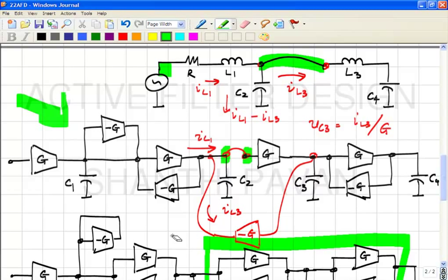You probably change the capacitors, right? You figure out two things to change. Rather, the combination of the two will change omega naught and Q. Okay, and you fix. You make sure that the omega naught and Q of the second order section is what you want. If you do this for every second order section and then cascade things, because the cascading process does not load the previous stage, it follows that the overall transfer function will be what you want.